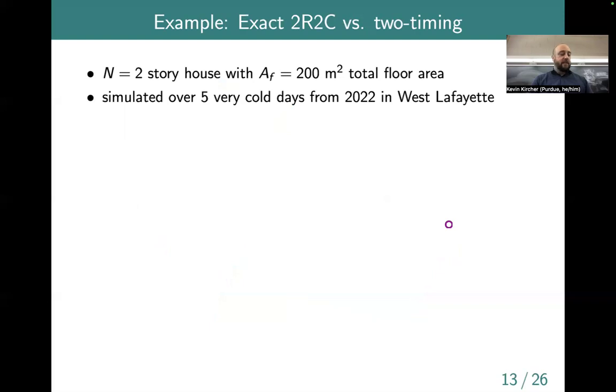Good question, thanks. Okay, I'm going to go through an example, which will probably take the last 7 or 8 minutes of class. This is basically the coding homework problem that shows up in your assignment next week. Let's do an example where we have a higher order thermal circuit, a 2R2C circuit in this case, and talk about a physical example of a house. This is like our test house that's a couple blocks away from here. A 2-story house with a floor area of about 200 square meters, about 2,200 square feet.